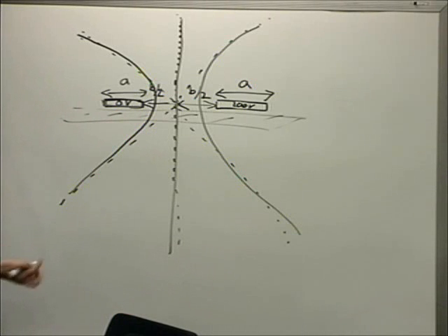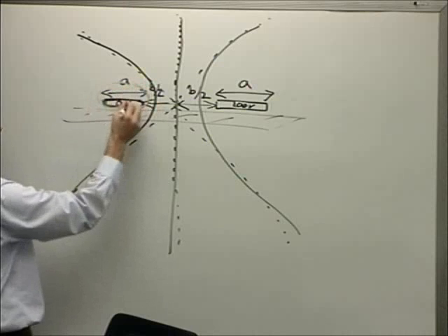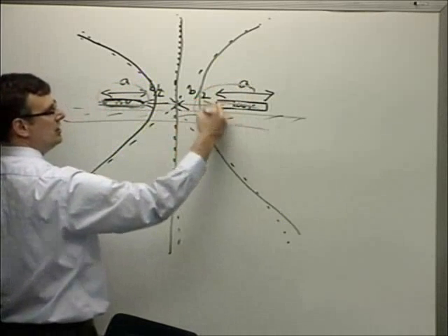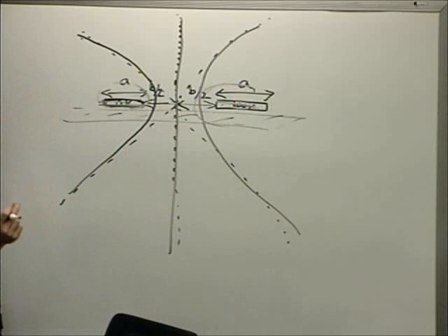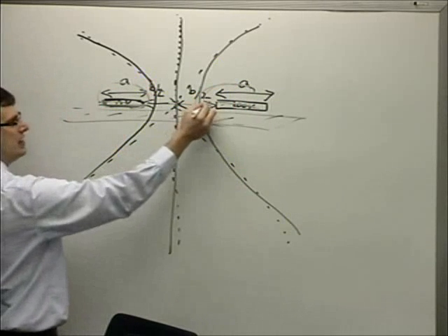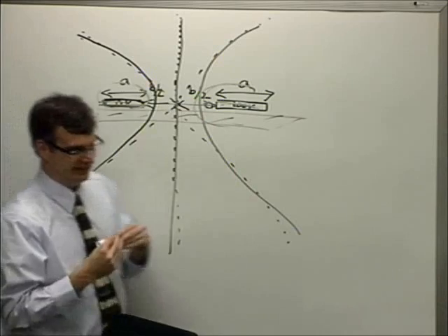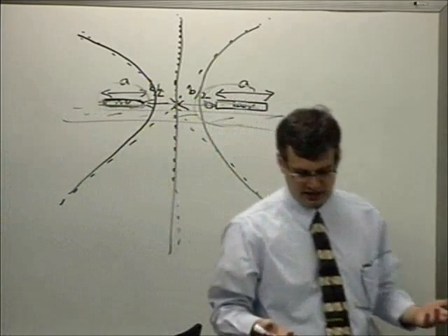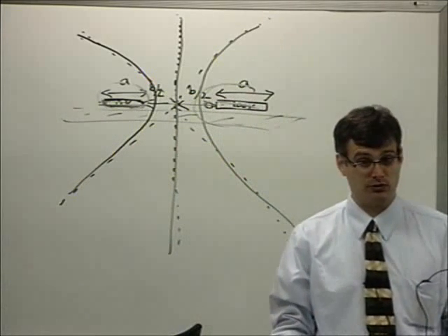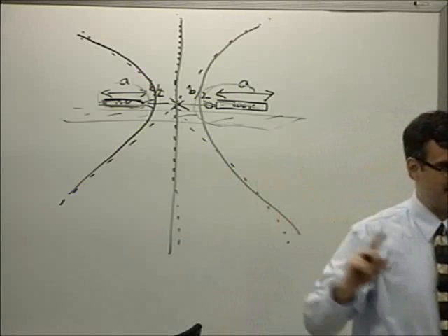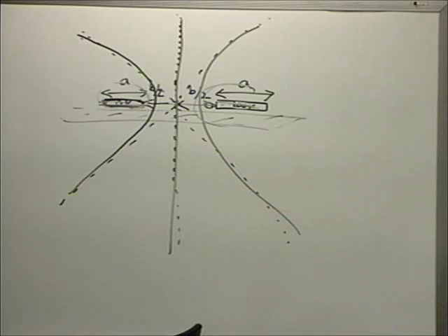So to solve this problem, we could use that solution as an approximation. It's a pretty good approximation because the area through here, the charge density across here and here, the field distribution here will be pretty similar. Only on the edge would you see a little bit of deviation. And so that's one of the questions that the bonus question was actually asking. How do you calculate the capacitance from this and come up with an actual result for this? Now, that's one example of where to use it. Where else might you use a capacitor like this?